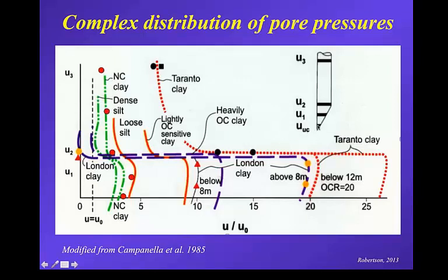So the shear-induced pore pressures have to far exceed the octahedral, and the theories can't cope with that. And so real soil behavior is a lot more complex, and the pore pressure distribution is a lot more complex. And also you've got the risk that the sensor may not be 100% saturated when you're starting from a negative number.